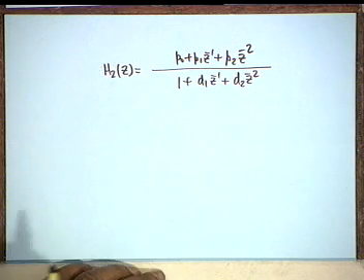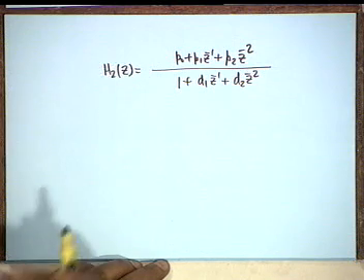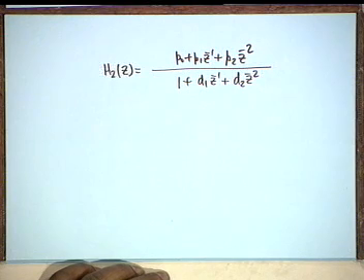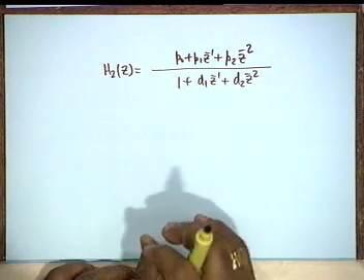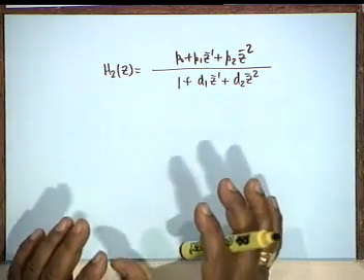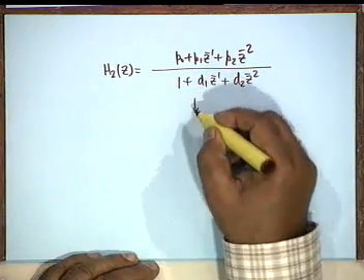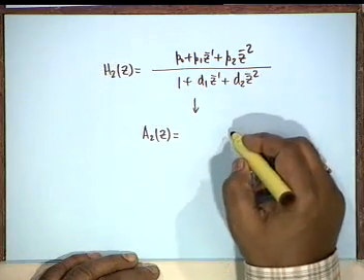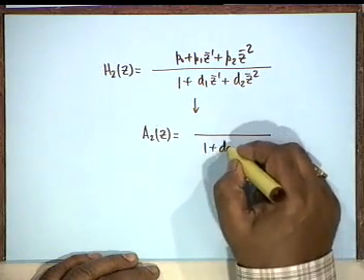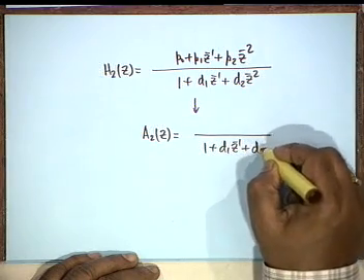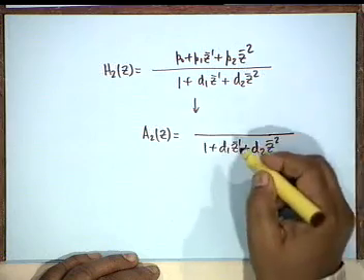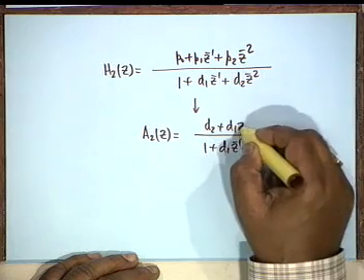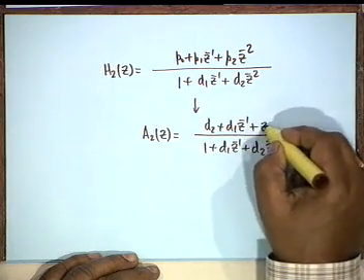That would make the lattice a more versatile structure rather than only being limited to all pass filters. Now, in order to realize this, what one does is the following. The first step is find out the corresponding all pass and realize this, that is 1 plus d1 z inverse plus d2 z to the minus 2, then d2 plus d1 z inverse plus z to the minus 2.